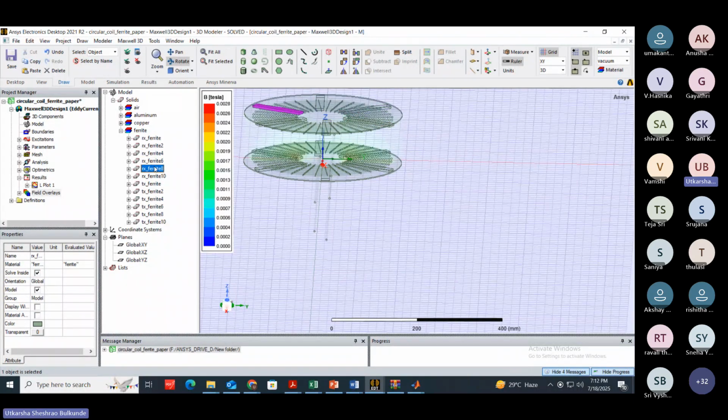You can use a plate also instead of these rods, but if you use rods, you will require less volume of ferrite and it will serve the same purpose. So your coupling coefficient will be somewhat less, but that will not affect that much. You will get a great saving in volume of ferrite. That's why instead of plate, I have placed rods here. You can keep plate also.